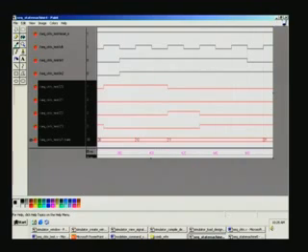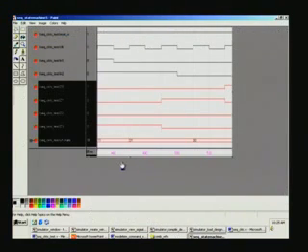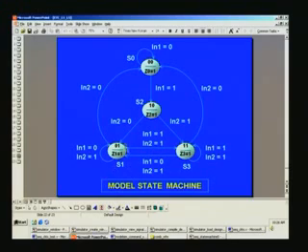So this verifies at random. And finally, we have one more waveform in the state machine. I think this is the path we have not covered, I suppose. Let us see whether it is. So let us say from S1 to S1 state, and then from there it is returning to 0 state. And let us see the condition here. So what is this here? 1 1. So input is 0 1 here. So in 1 1 state with 0 1 we have to look into this one. Is it 1 1? Yeah, it will go to S3.